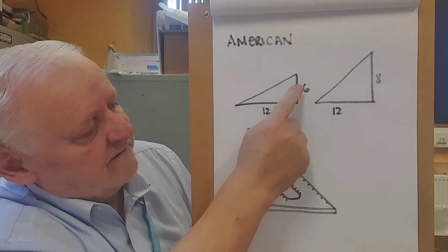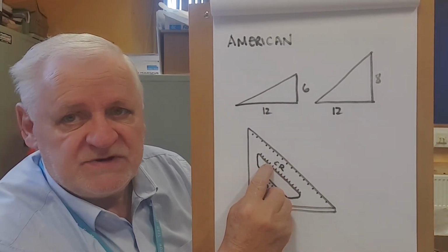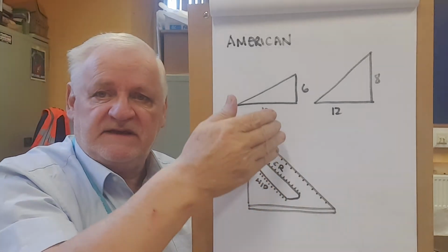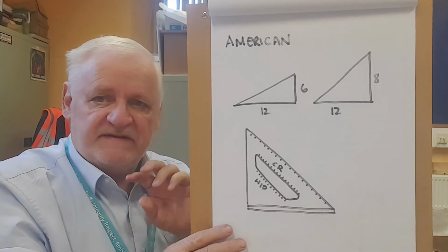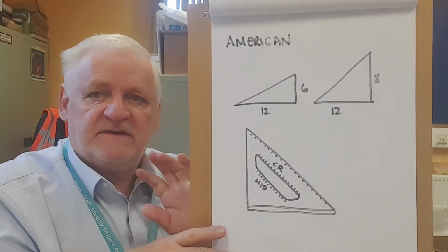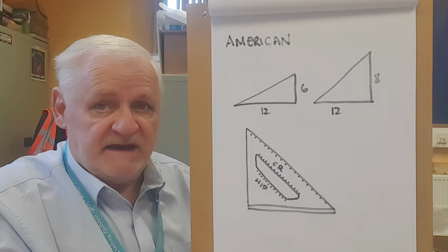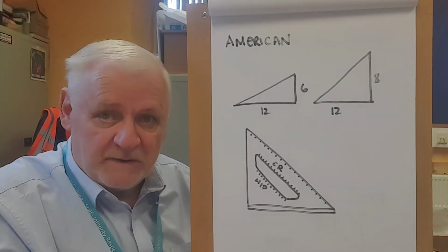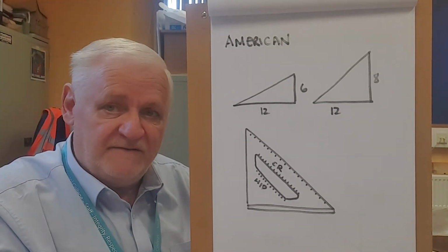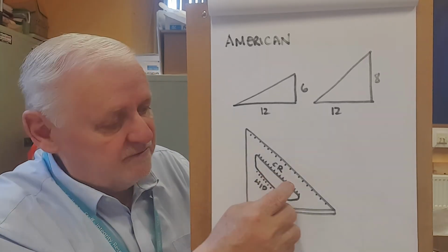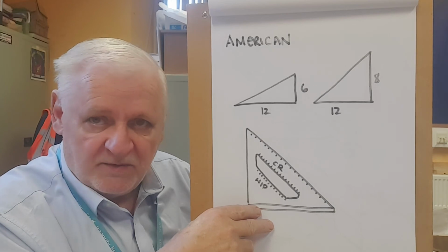So if you're doing a 12/6 roof, you pivot it to where it says number 6. And once you hit the number 6, it will automatically give you your plumb cuts and your seat cuts. You can just pick it up every time, move it to number 6 and strike the plumb cut and the seat cut. So that's very, very handy. But that's handy as long as you're not on something that's in between a 6 and a 7, or in between a 4 and a 5. Then you might have to revert to the protractor, which is a little bit more complex.